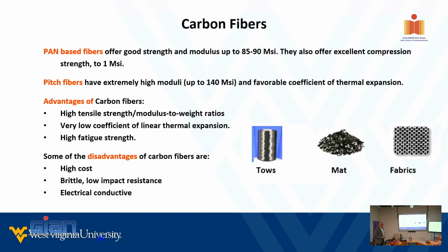But the problem with carbon fiber is that it has a chemical corrosion problem, what we call galvanic corrosion. So we need to be careful. You may not want to use that in civil structures where it's exposed. Do you know, by the way, India has 7,000 plus kilometers of coastal line?